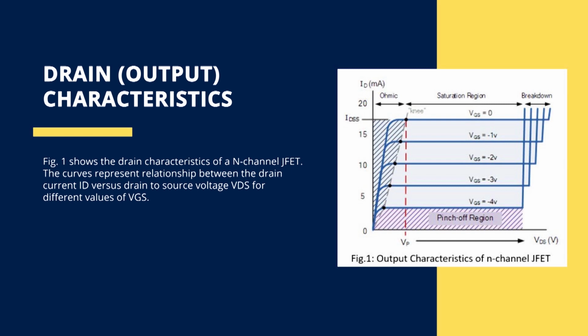When we apply the drain voltage and keep the gate voltage constant, at the starting case when VDS is very low, almost no current flows in the circuit. The drain current is very less. When VDS increases, the curve goes into the ohmic region and the current increases with the applied voltage. This increase continues and a pinch-off voltage is reached.